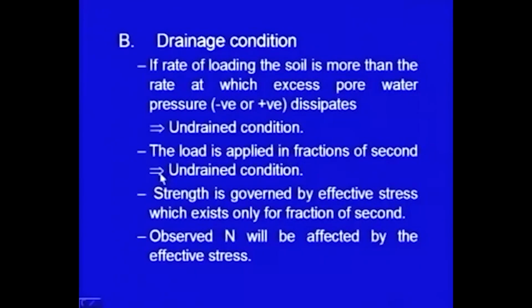So, if the soil is not drained, the rate of dissipation of pore water pressure is low, then undrained condition will develop, and the strength, as you know, is governed by the effective stress, not the total stress, and that effective stress in this case will occur only for fractions of seconds. So, the observed N value will not be the true value, it will be some apparent value affected by the effective stress.